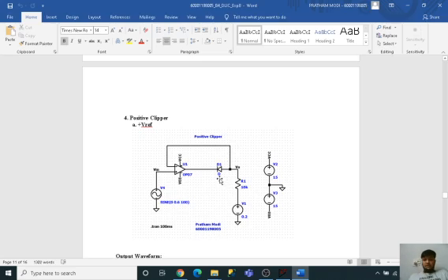As the normal cut-in voltage of a diode is 0.7, the input has to be less than or equal to 0.7. And for the sine wave input which I have been given, the Vref, this reference voltage, has to be less than the sine wave signal.